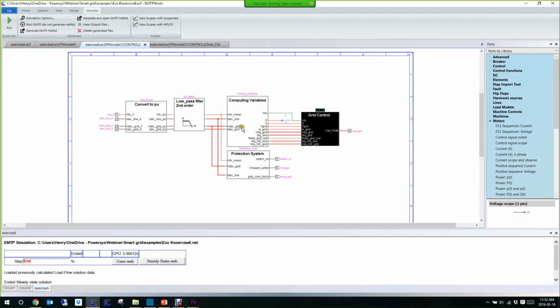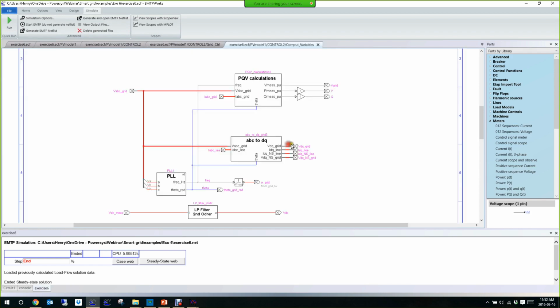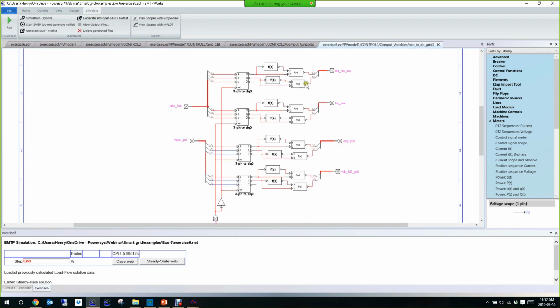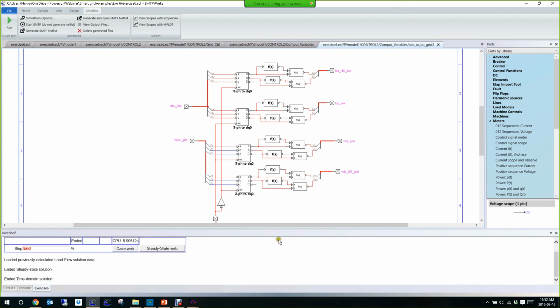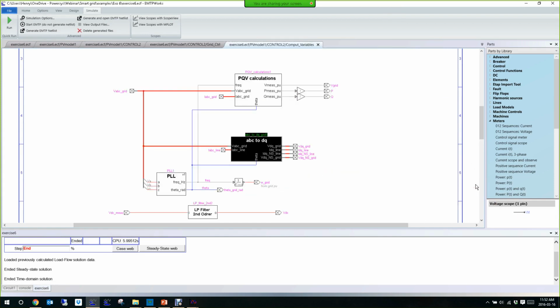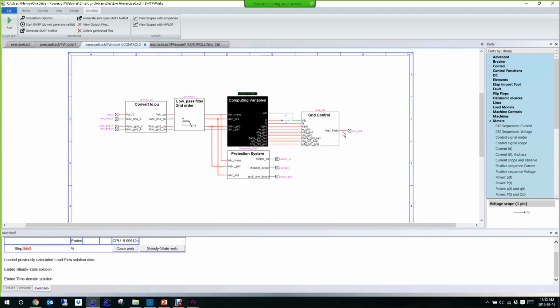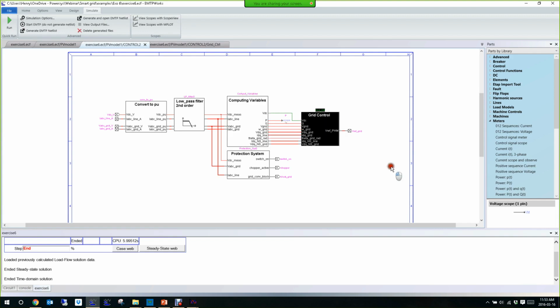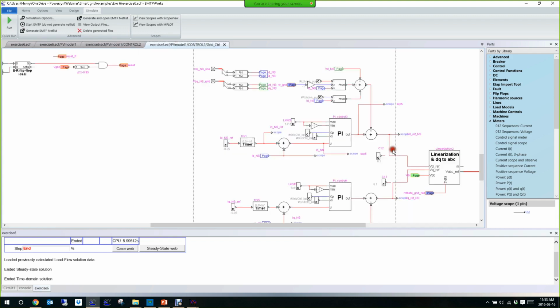So what do we have to do? We first have to calculate the negative sequence DQ0 component. It's actually very easy to do. If we go in the ABC to DQ0 calculation, we use the same function as usual, but instead of inputting omega t, we input minus omega t. In that case, we find the negative sequence DQ0 component. Of course, then we have to filter the second harmonic. We inject some second harmonic in the current, but for the loop, this second harmonic is not convenient for the DQ0 transformation, so we remove it from the signal, especially for the positive sequence loop.